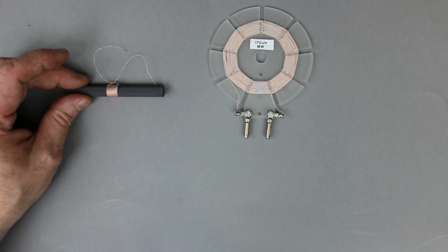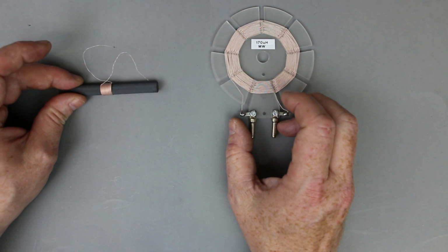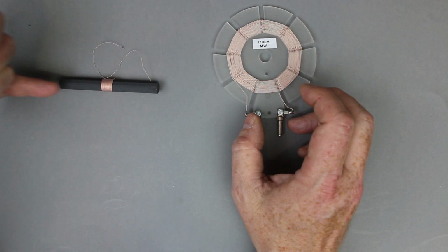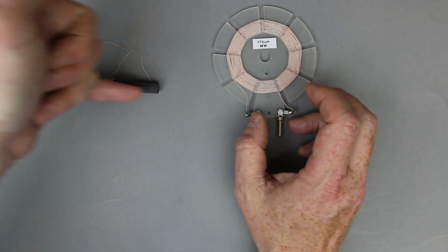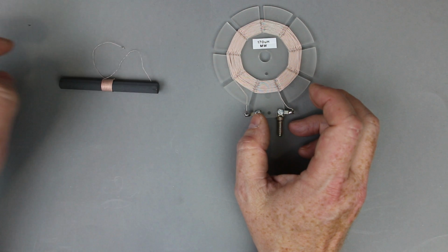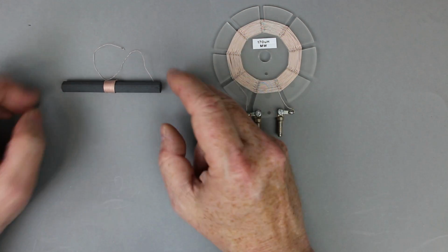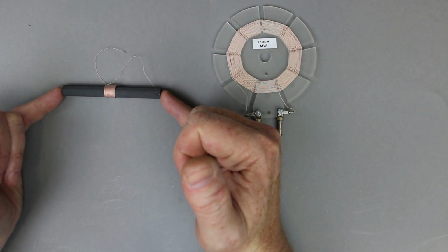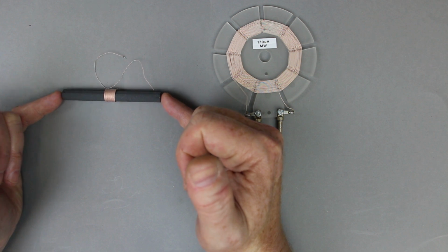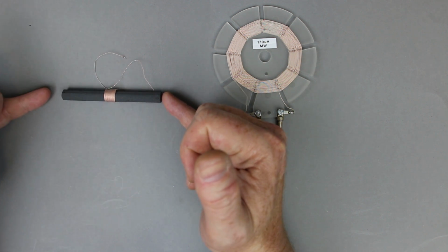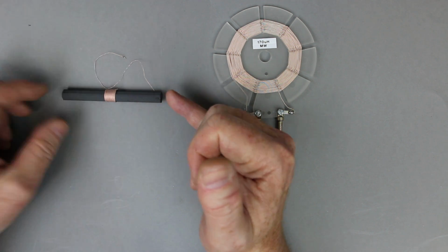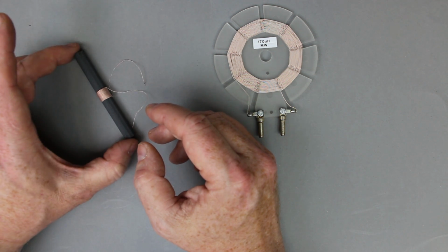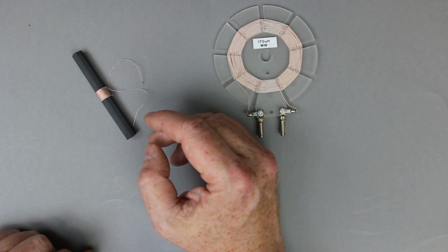That's totally different with these magnetic coil antennas. You have zero sensitivity in the direction of the rod, which is perpendicular to the coil windings. This means if you have an interfering station near your receiving frequency or even exactly at your receiving frequency, you can blank out the interfering transmitter by placing the antenna rod exactly in the direction where the interfering signal comes from.